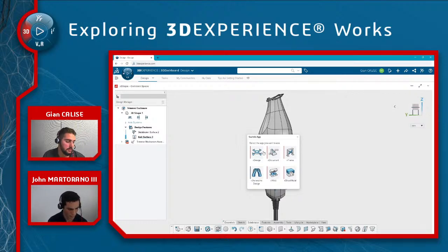Neil is asking us, which types of advanced mates specifically did you use for the mechanism? Well, you might have noticed before that we had a rod going through part of that shaft connector. So that's kind of what restricted it from moving up and down. So the only advanced mate we actually needed to use was that slot mate that you saw us put in.